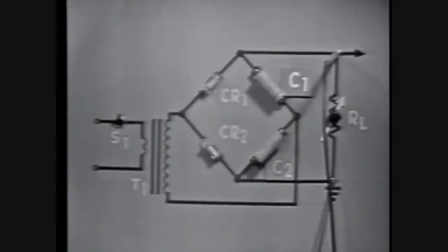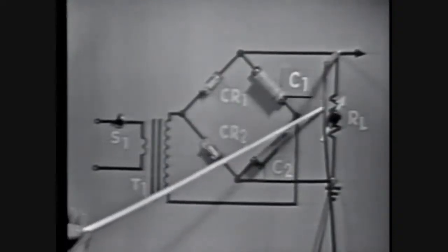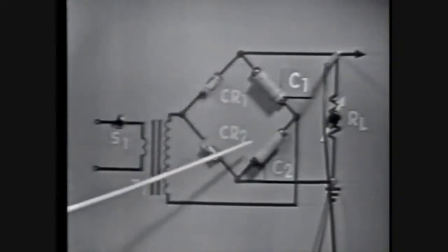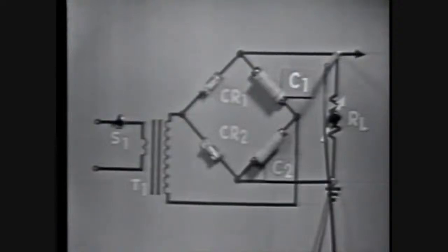With a long time constant, where the resistance is high, average output voltage is high. If the load on the circuit increases, resistance decreases, and this decrease in resistance shortens the time for one time constant. This then allows the capacitors, that's C1 and C2 in this circuit, to discharge a greater amount between cycles of the input. So, average output voltage decreases.